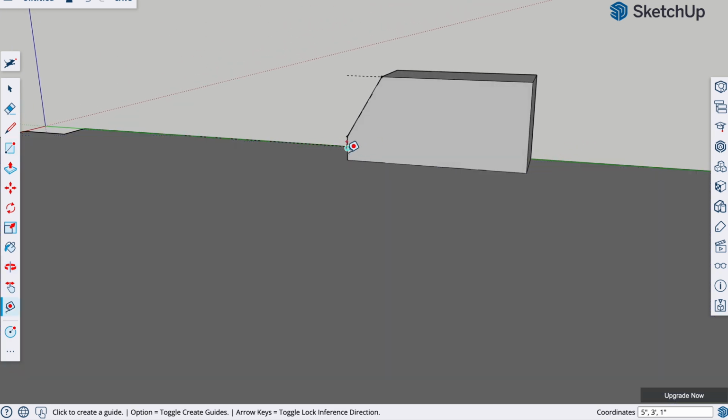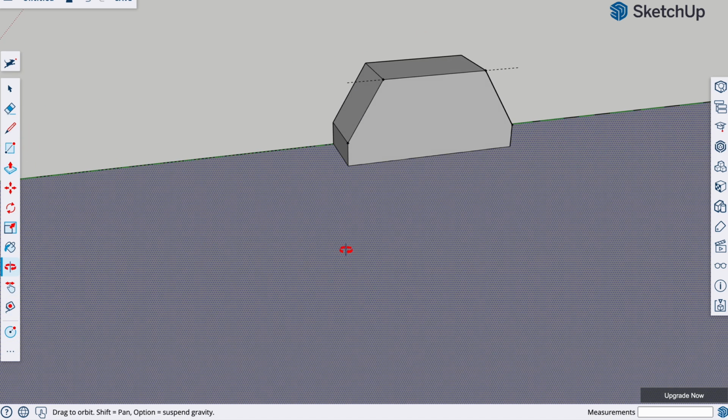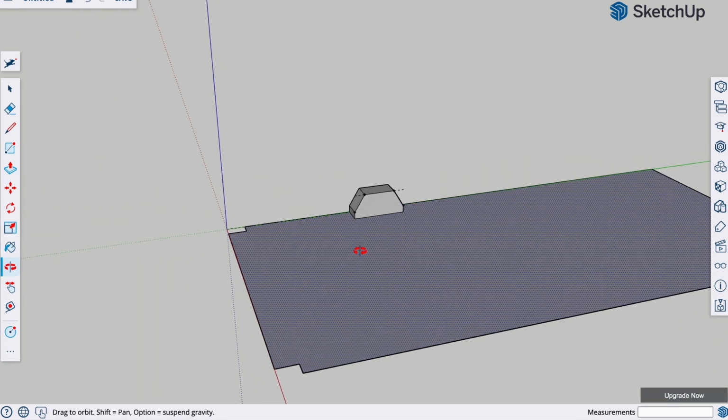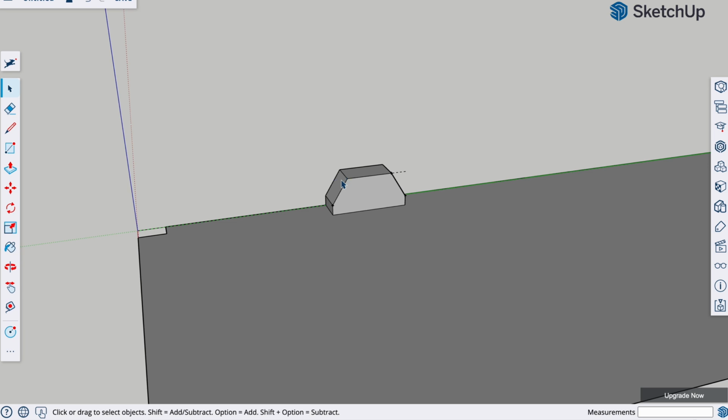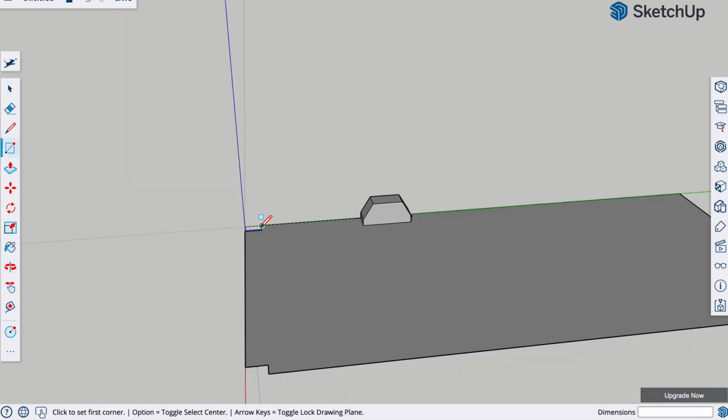Because I forget, we're going to hit T. Okay, so we did 2 inches up. Tape measure, bottom corner, type 2 inches up, drop a guide point. Same thing here. Drop a guide point 3 inches in, hit L to draw a line between the two, connect the 2 points, use the push-pull tool, and pull it out. So you can then see your wheel well. What I would do is click on these small lines and delete them. You can also delete your guide points if you would like. So we did that on one side. Let's quickly do it on the other.